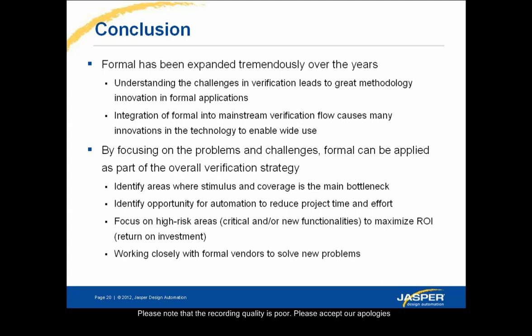Yeah, I guess my question was more on a fundamental level as to what exactly should be the notion of coverage for formal. I don't believe the traditional notions of coverage, functional coverage and code coverage for simulation, actually are applicable. And I understand that if you have a simulation-driven coverage metric in place, then you can try and merge the results from coverage from formal and so on. But why are we doing formal to solve a certain problem? Because we want to get there exhaustively. And then to say that actually I can't get the coverage, so let's harp on simulation, doesn't quite make sense to me, if you know what I mean.